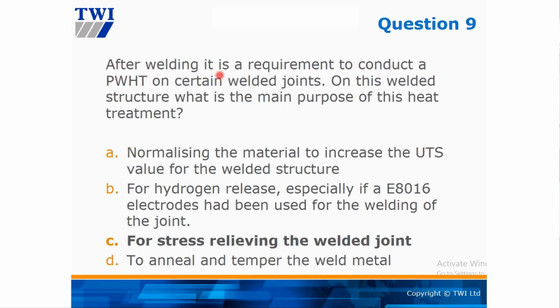After welding, it is a requirement to conduct a post-weld heat treatment on certain welded joints on this weld structure. What is the main purpose of this? So post-weld heat treatment always reduces the stress. So that's where the answer goes to C.